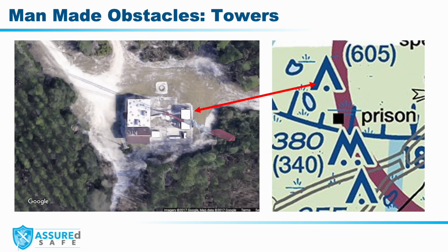Towers are particularly challenging to fly near. Guy wires can be hard to judge through depth perception because of their relative size, and they don't show up well on mapping software. Luckily, the FAA sectional charts are comprehensive and updated regularly for tower markings.